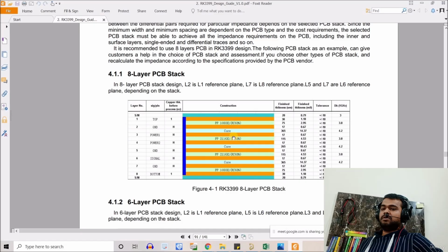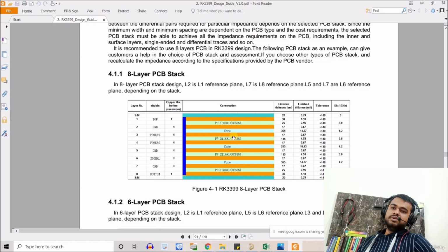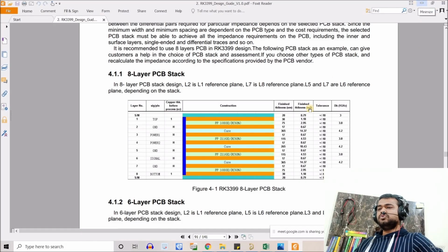for example, let's take RF. For RF, we basically try to avoid ground with the radio frequency antenna connections or antenna routing. We try to avoid ground there, right? So in that case, we'll try to remove copper underneath that, or we just want the maximum space between those tracks and the copper, right? So I hope you're getting my point here, and this is how you are able to decide.